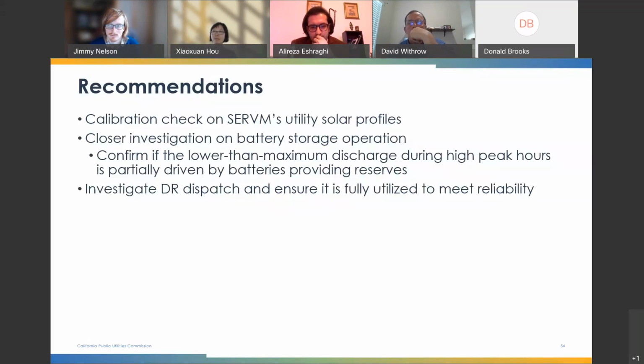Okay, great. Yeah, I'll be happy to provide some comments on the reg down and commitment. So on the reg down, just to confirm, the optimization does include reg down as one of the variables that it uses. Generally, though, if you look at the commitment for the other variables that it's trying to optimize for, there's going to be some inherent reg down in the system in most hours, except for during curtailment hours. And to serve that reg down during curtailment hours, you just curtail more to provide that reg down. So it's a fairly straightforward problem that gets solved within the solution mechanism that we've got in the model. So it does always provide the reg down.